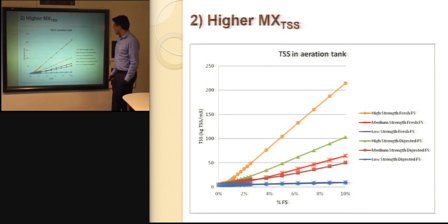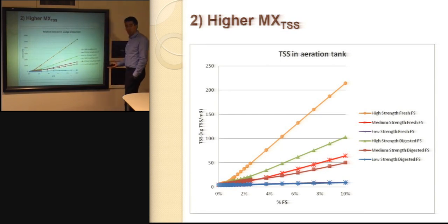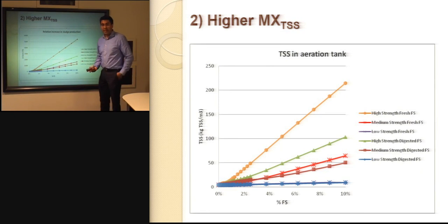That will, because of the accumulation of solids, immediately cause a considerable increase in the sludge production. There will be more solids being accumulated in the plant, not only because of that degradation, but also because of that accumulation of particulate organics. We are only moving solids from one point, and we are adding those solids into the system.